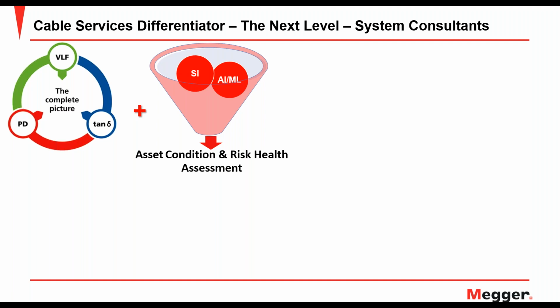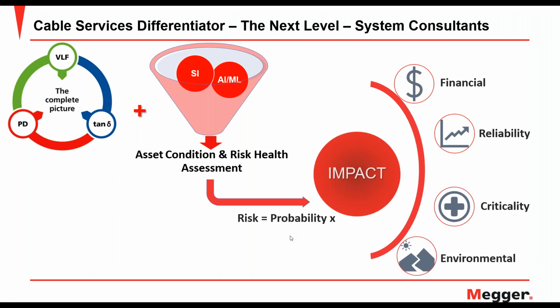We can actually look at leaking bushings at transformers and report them, as I mentioned before, and whether the arrestor is in place. If it's not there, then maybe it should be put in there. But basically, we're looking at risk of failure, and also the probability of failure. Risk is the probability of failure multiplied by the impact of failure. This means that the total amount of risk exposure is the probability of, let's say, the fault occurring multiplied by the potential impact or the damage incurred by the event.